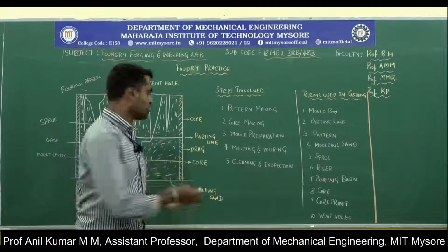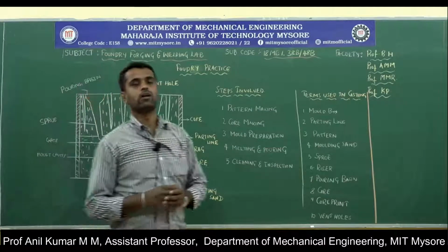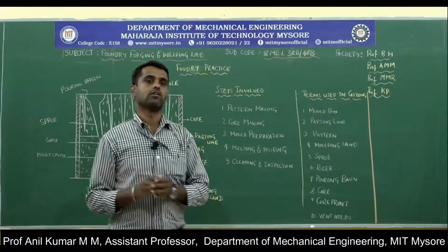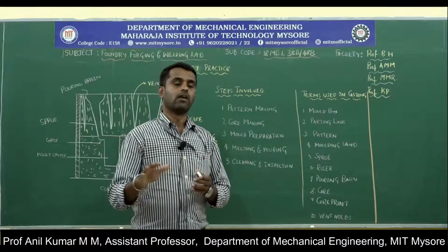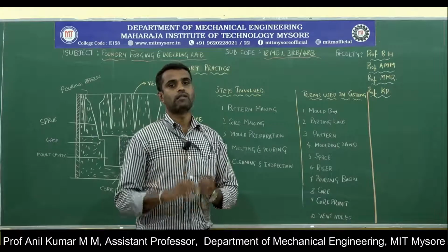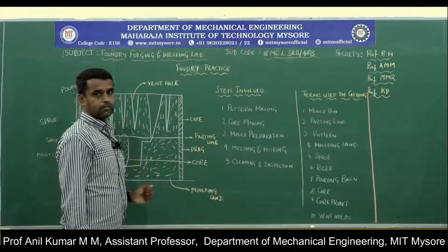After solidification, you take out the solidified part and remove the unwanted materials, that means adhering sand particles, runner, and riser. Then that solidified part is the casting.